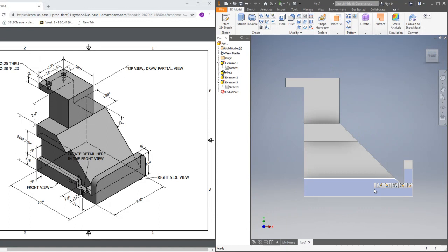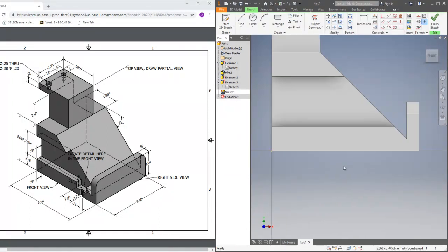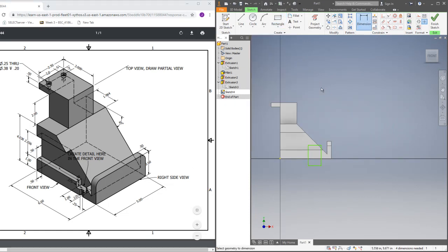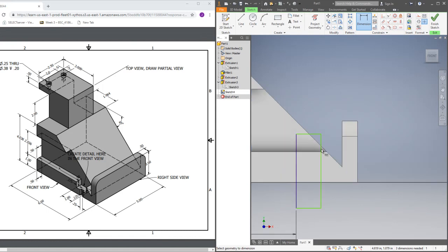So now put a new sketch on this, and inside here, I want to put me another little rectangle. Just throw me a rectangle in here, and it is going to be 4 from here to here. So dimension from there to there is going to be 4. Okay, and the overall of this is 1 inch. So boom, put that in there.